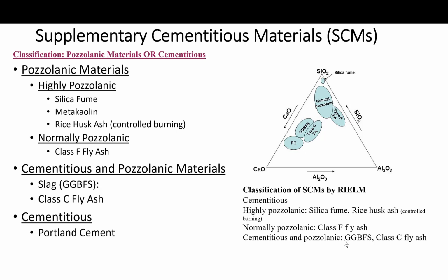The mineral admixtures can be classified into three main categories: pozzolanic materials, cementitious materials, and non-reactive materials. Typically, the first two categories are used as blends with the Portland cement to form one product, blended cement. This practice is more common in Europe than in the US. Otherwise, these materials are added by the concrete producer to the mix as a supplementary cementitious material.